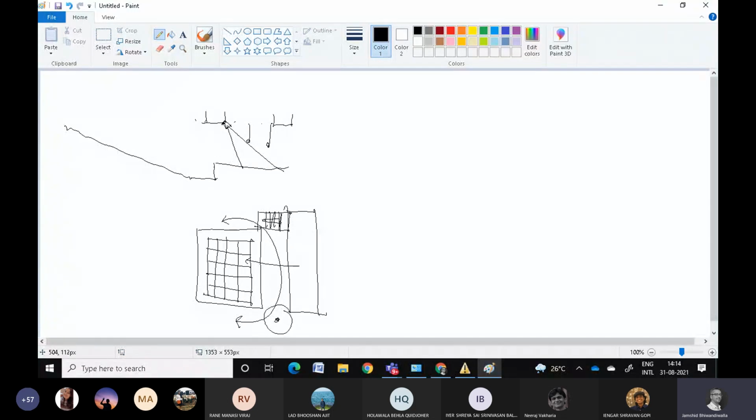You need to decide how the catwalk is connected. Most of the time the catwalk goes and connects to the sides, preferably where your columns could be. So if your columns are somewhere here or here, any of the columns that are there, then the depth of the catwalk actually acts as a beam. So this entire thing acts like a beam in some sense.